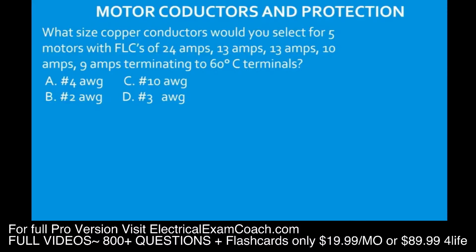What size copper conductors would you select for 5 motors with FLCs of 24 amps, 13 amps, 13 amps, 10 amps, 9 amps, terminating to 60° C terminals? Now this one can look like a bear at face value, but once I explain it, it's not very complicated.